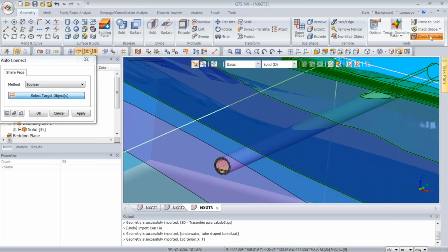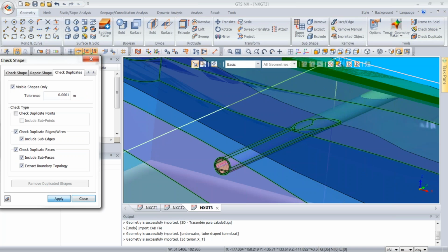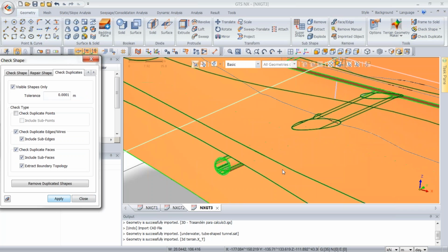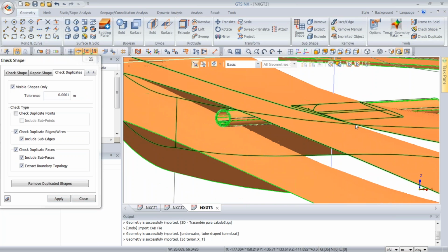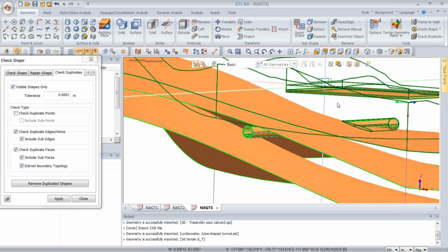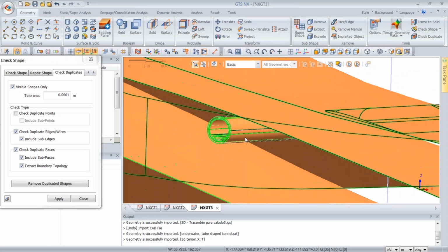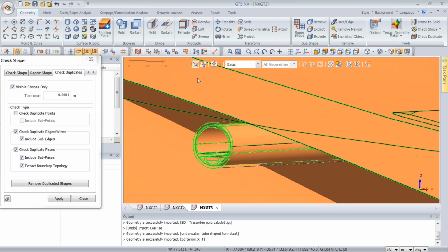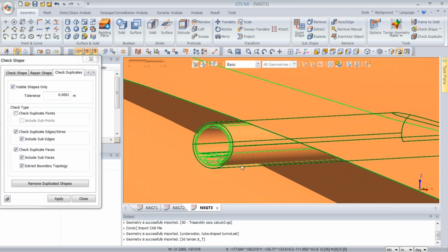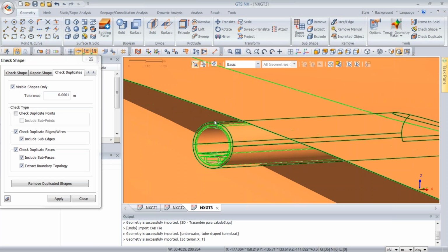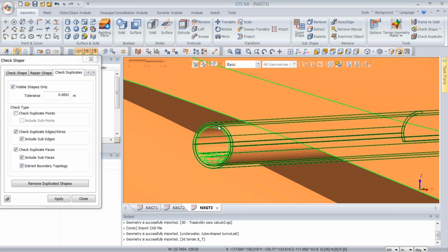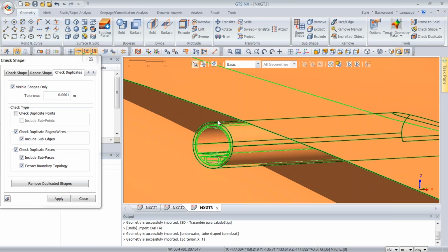Visually, we have this tool called here, check duplicates, that will light up in orange the faces that are being shared. It's a program basically recognizing contact. So we see that the faces are orange between the layers, the raft, and you can see that the layers are orange for some parts of the tunnel, but you can actually kind of catch near this edge and near this edge that it's somehow only the inner tunnel lighting up in orange, but not this outer tunnel.